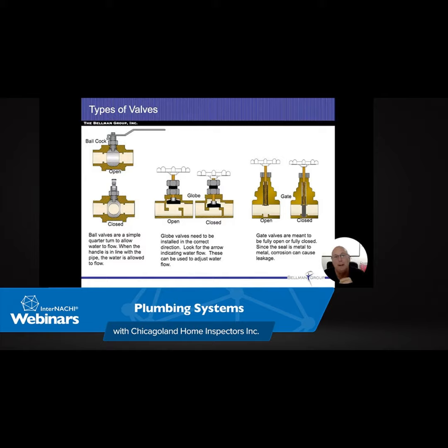The same thing can happen with those garden hoses. These little anti-siphon devices are like $5 or $10. So even if I have an old faucet that doesn't have an anti-siphon, for a lousy $5 or $10 item, and all they have to do is screw that on the bottom of it, we take away even the most remote chance that we'll be able to siphon any of this water back into our system. All right? So I like to encourage that as well.